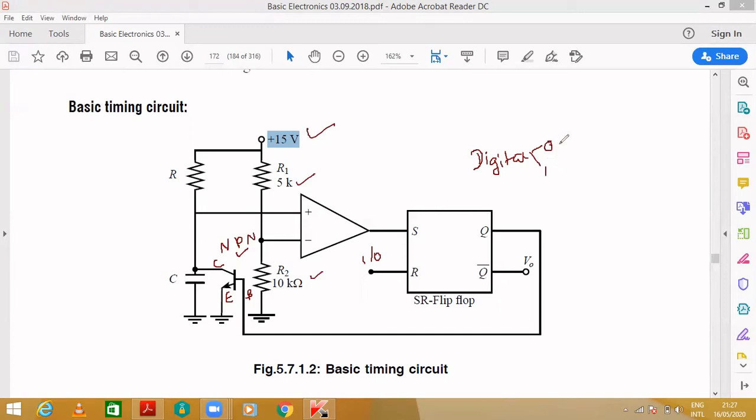It can have a 0 or 1 value for R. This is an SR flip-flop. S is nothing but set, and R is nothing but reset. Why is it called bistable? It has two outputs, and this is just the complement of this. Suppose Q equals 0, then Q bar, as you can observe here, is the complement, 1. If Q is 1, the Q bar will become 0, complemented values.